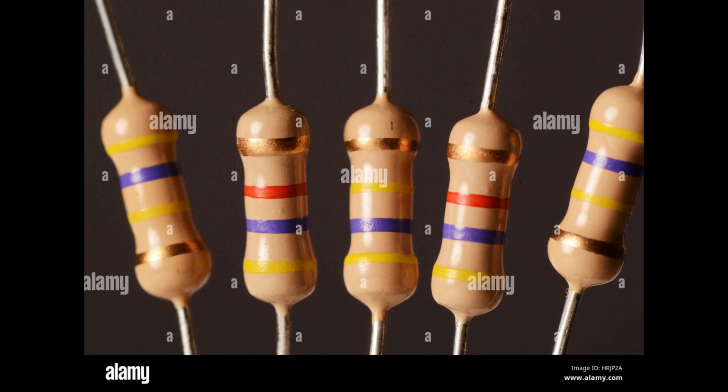Negative temperature coefficient, NTC: in resistors with a negative Tc, the resistance decreases as the temperature rises. This means that the resistance value becomes smaller at higher temperatures. NTC resistors are commonly used in applications like temperature sensors and self-regulating heaters. TC values: the temperature coefficient can vary widely depending on the material and construction of the resistor. Common TC values for resistors are expressed in ppm/°C and may range from around 25 ppm/°C to 5000